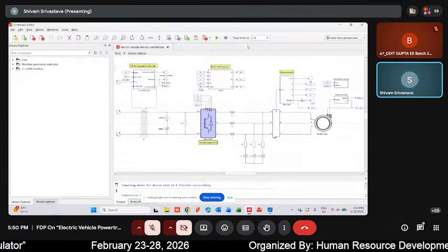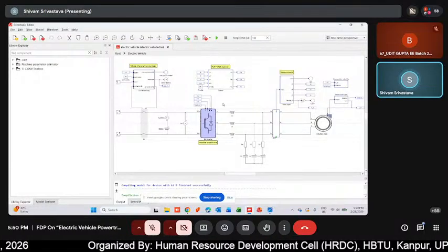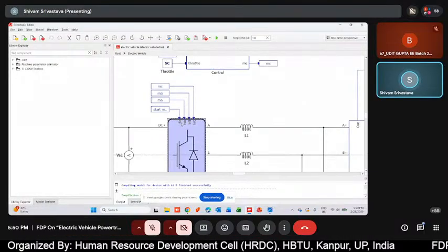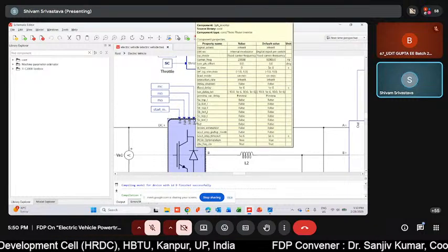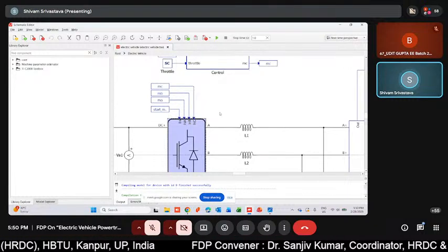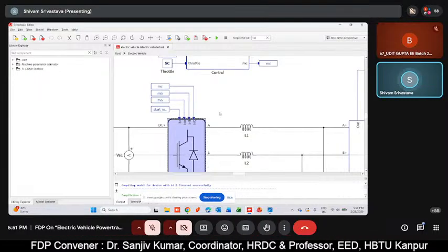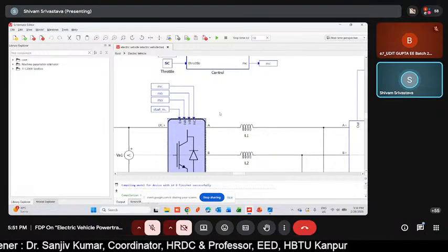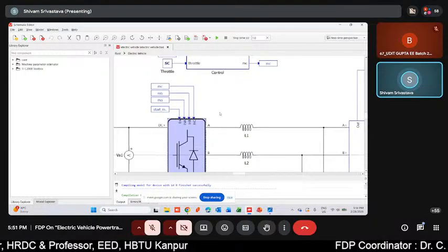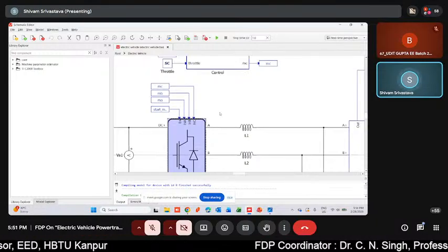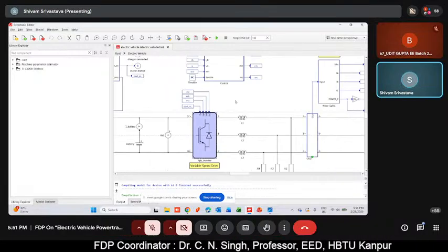After selecting the three-phase inverter in the internal modulator, you can see four tabs available by the name of enable, INA, INB, and INC. Enable is for enabling the inverter to turn on and turn off, while INA, INB, and INC are for accepting the PWM signals for different legs, phase A, B, and C, of the inverter.